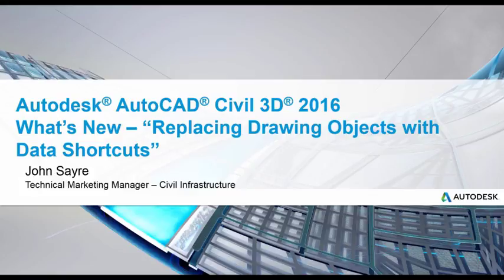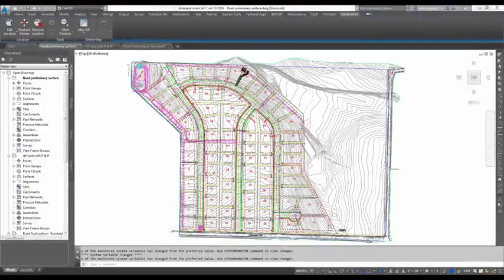Today I would like to talk about one of the What's New features in AutoCAD Civil 3D 2016, replacing drawing objects with data shortcuts. We now have the option to use the Manage Data Shortcuts command to repair broken data shortcuts and to replace drawing objects with data shortcuts.